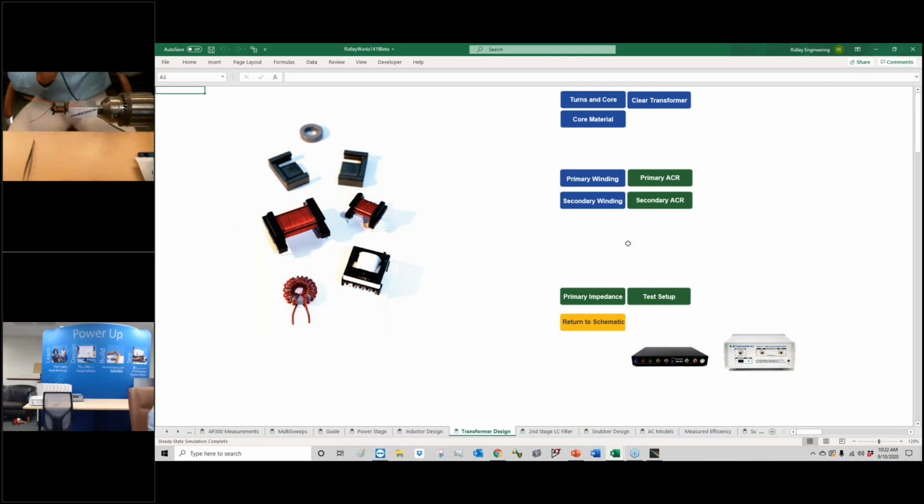soldering iron comes along. This is where you enjoy your cup of coffee. So I'm going to heat this, and I'm going to use the solder to burn through the insulations on the windings. And this is where quality of design of the bobbin helps. You want to have a plastic in the windings that doesn't melt with solder. When I started in this industry, that wasn't possible. It always melted the bobbin, so you have to be extremely careful.